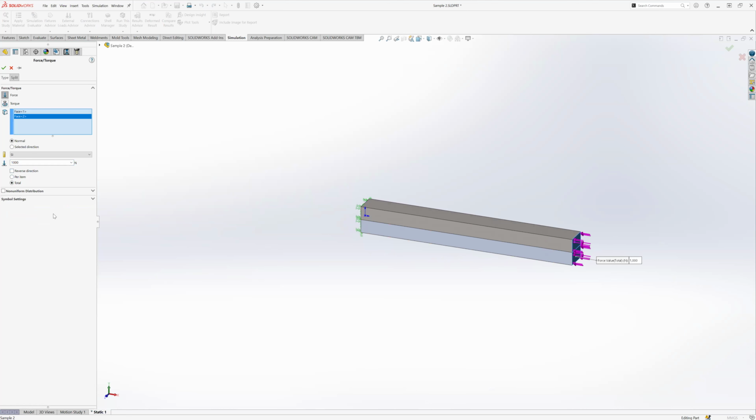If you select several faces and you have 1,000 newtons with per item, everything you select, whether it's an edge or whatever, is going to get 1,000 newtons, or whatever you specify. So that's something to be careful with. You can end up getting double the force you want.